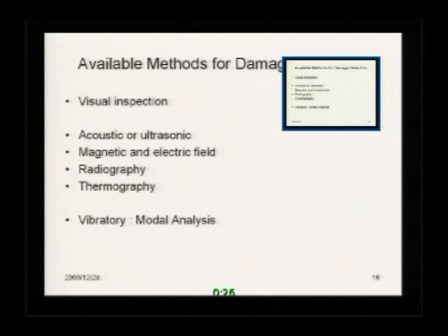They give you a list, and the list will say: can I see any rusting on the rails, can I see any cracks on the bridge surface, can I see any cracks in the supporting structure? You just look at whatever you can see and list those on a form.